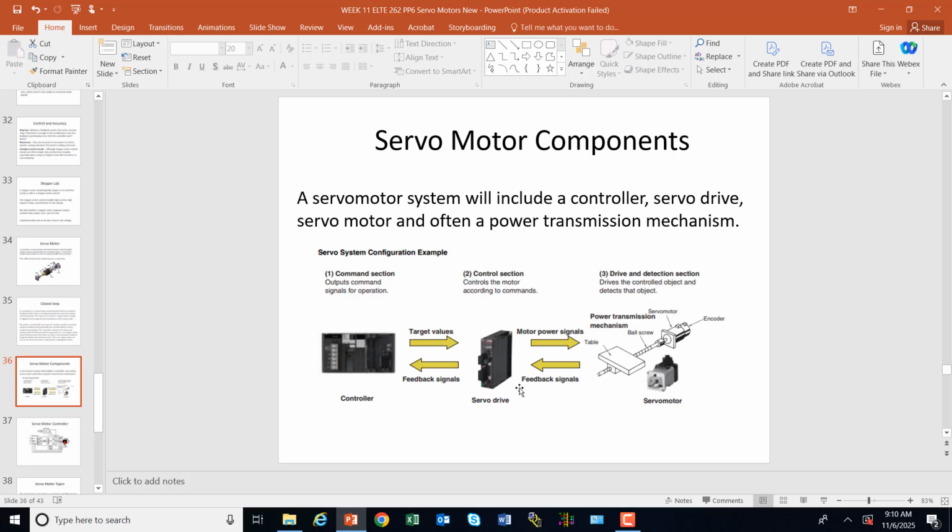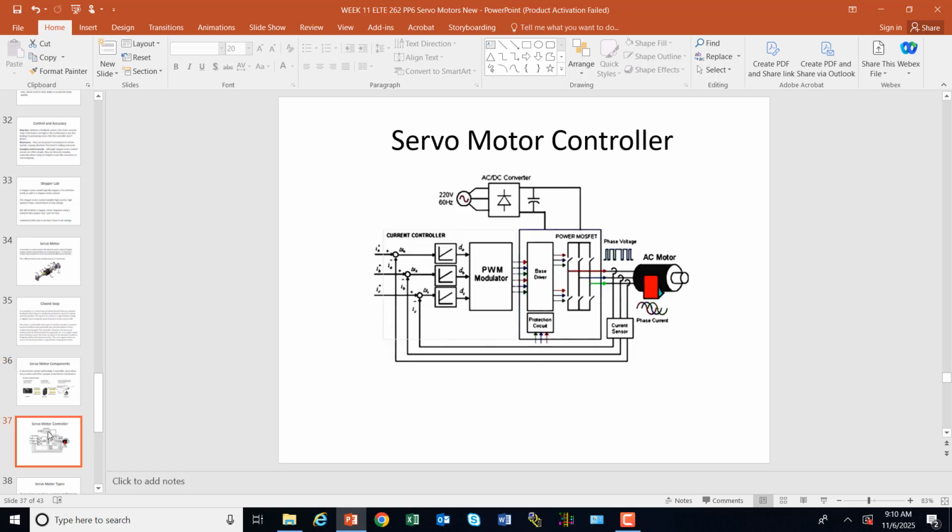But another example of this is like a robot arm. The robot controller is a big servo drive controller, and the robot arms each have a motor on them, and there's no extra sensor to be sure that the robot arm went to where you said it would. But on the back of the servo motor, there's a sensor that says, hey, I've turned this many times, the arm should be here, and it pretty much is going to be where you want it to be. You could add another analog sensor to a robot to be sure it gets where you want.